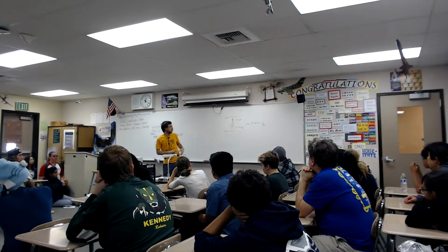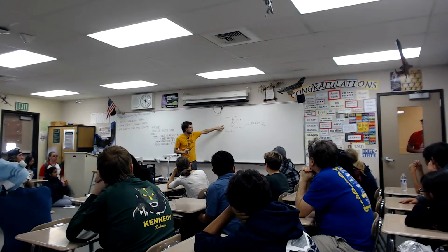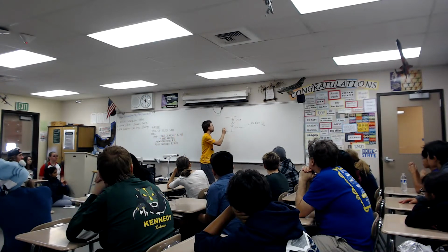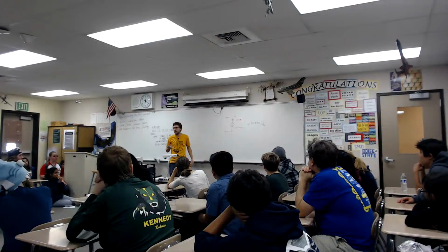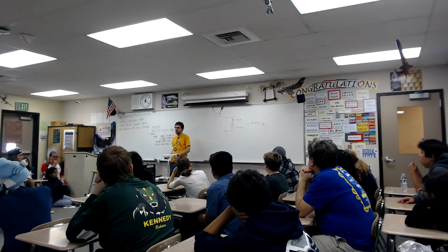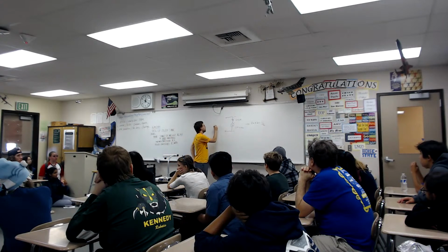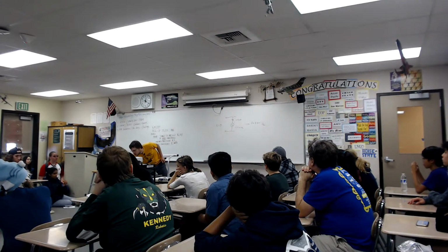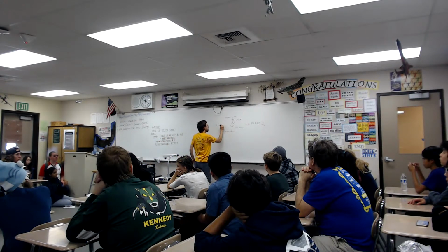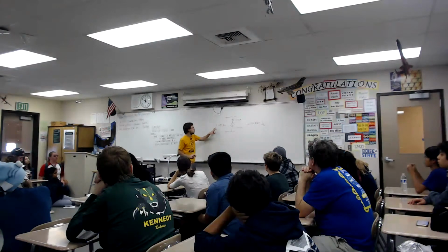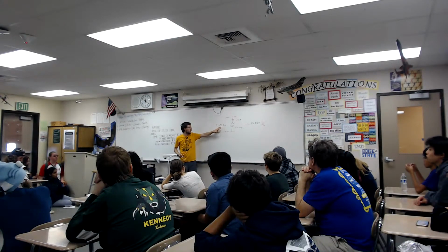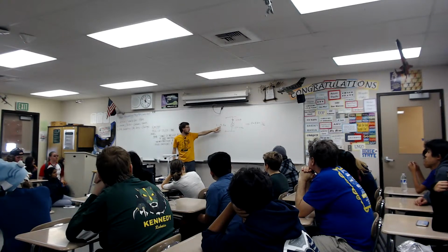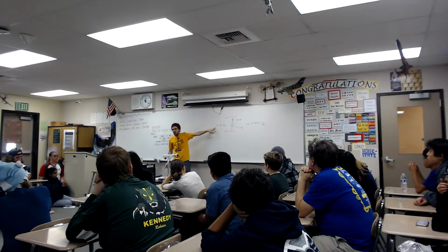So there's one other equation, which should also be useful. A motor is an electromagnet. As you pass current through the windings, you're going to get more magnetic field. So the torque out of our motor equals the current times KT. This says as we get more current, there's some constant of proportionality correlating the current through the motor with the torque coming out.